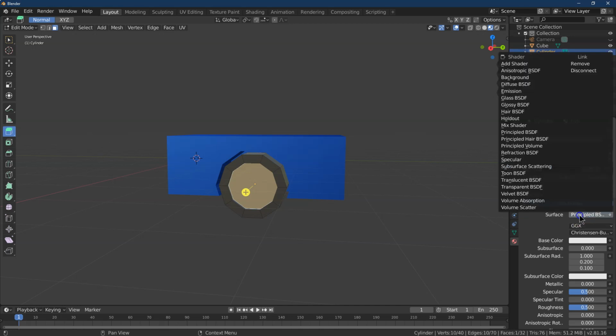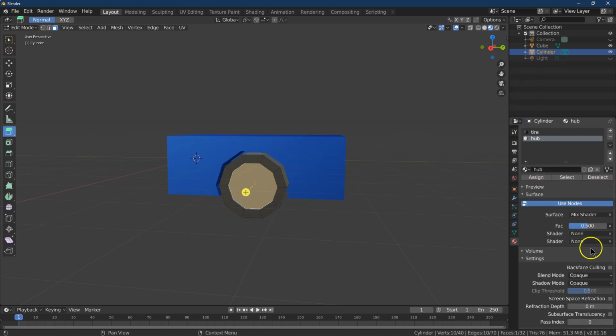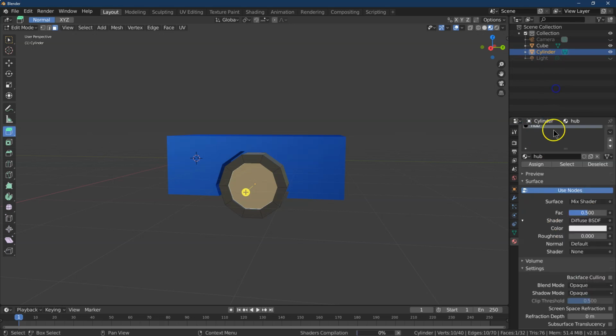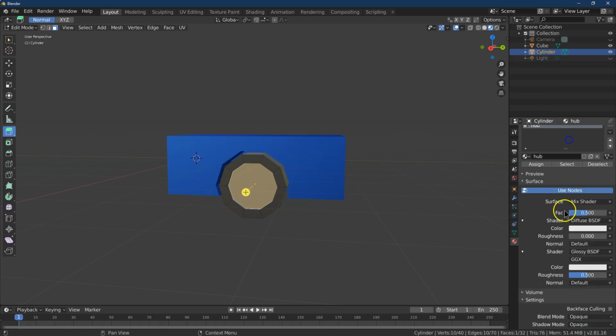And let's make a shiny material. So for that, I'm going to use a mix shader. What's going to be involved in my mix shader is a diffuse and then a glossy. Now, the roughness here is going to be 0.2 for the diffuse. A silver that I really like is 90, 90, 90. And then for glossy, the roughness will be 0. I'm switching this to sharp, and the color again will be 90, 90, 90. Enter. And that is looking good.